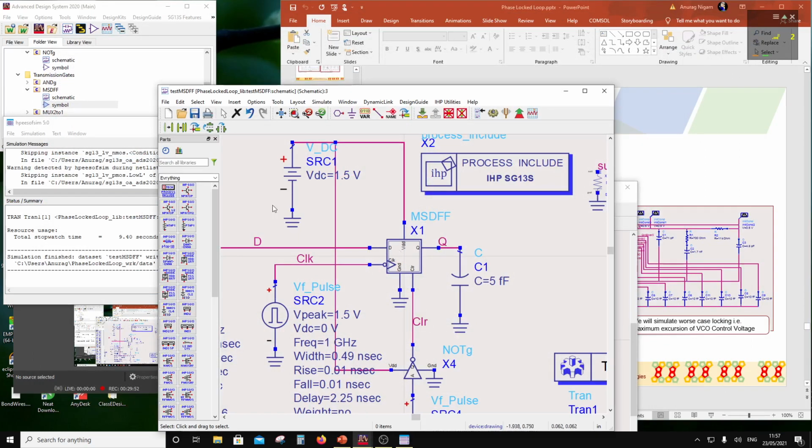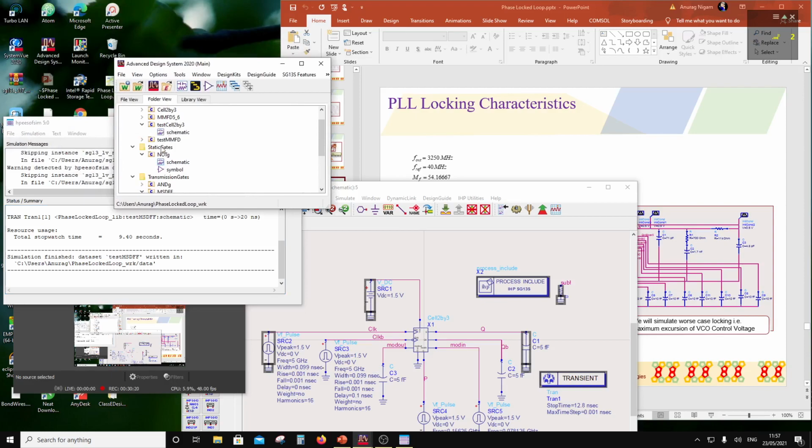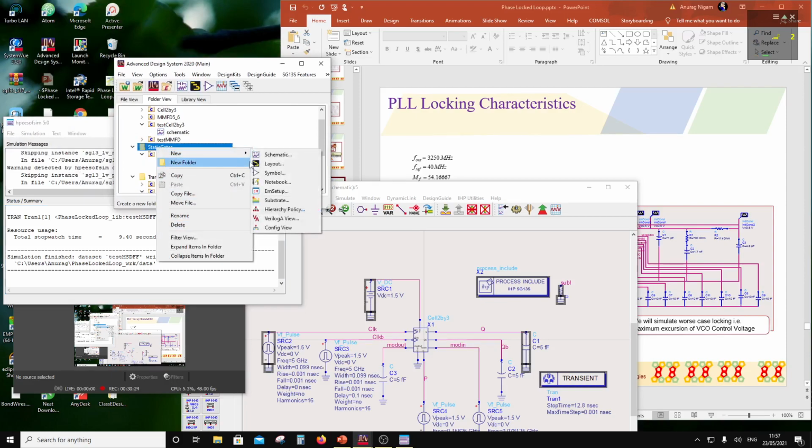Now what I'm going to do is I'm going to do a adder, a full adder. Because in an accumulator I'm going to have a master slave D flip-flop giving a clock delay of 1 clock, and then it is going to add to itself. So that would be the adder, right? So I am going to implement a full adder. So I need a full adder. I can implement using static gates because this is not going to go up in frequency.